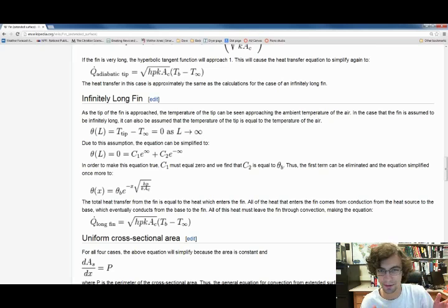So we tend to think of that as a steam temperature, but that is an assumption in and of itself. It won't actually be the temperature of the steam. You might look into that assumption, but we'll take theta sub b to be the temperature of the steam minus the temperature of the ambient. And so it's multiplied times this exponential term scaled by a distance x, and it includes, as you can see, the convective heat transfer coefficient